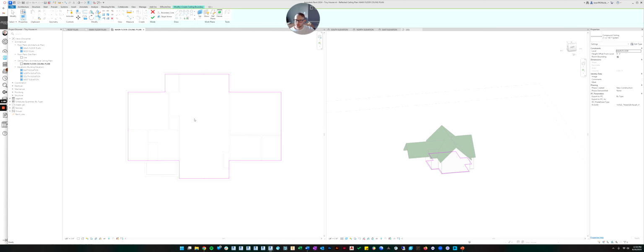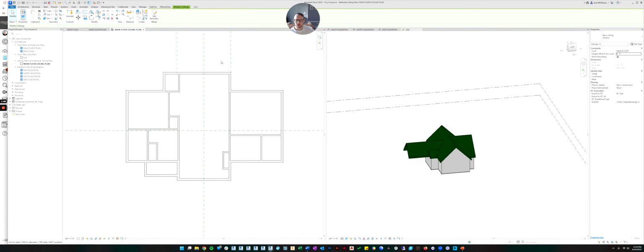And I'm going to trim those. And once again, we're going to look and see what kind of ceiling we've got. For now, it says gypboard on wood furring. I'm just going to choose a generic for now. It's currently hosted to the main level, and then it goes up 9 feet. Oh yeah, that's fine for now. We'll just keep it 9 feet off of the main floor, and then we'll click OK to close the sketch.